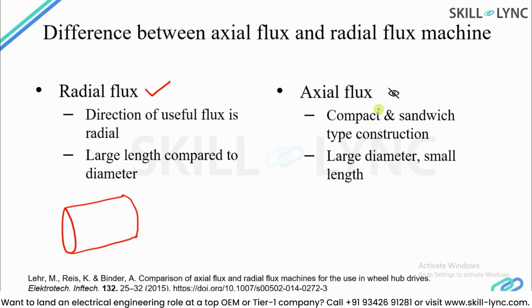And an axial flux motor is basically a compact and sandwich type construction, and their diameter is large but length is small. So if I draw this kind of a motor, it will be something similar to this, where its length is quite small, and this can be another arrangement of, let's say, two rotors and a single stator in between.